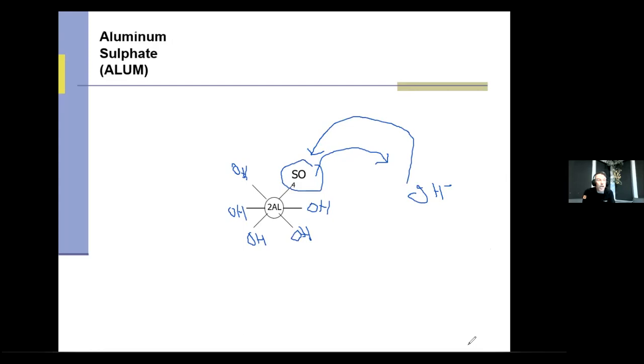Unfortunately, it's a lot to make this work, but the reaction is so much better, so much more efficient, and you use way less product. You'll use probably 50% less product or coagulant, which means you can have smaller pumps, smaller tanks. It just works a little bit better. But again, there's a trade-off with cost because the product itself does cost more.